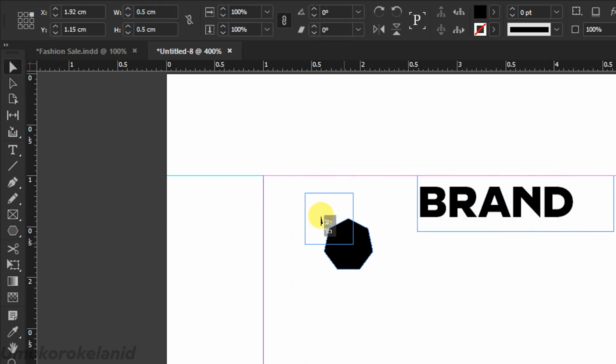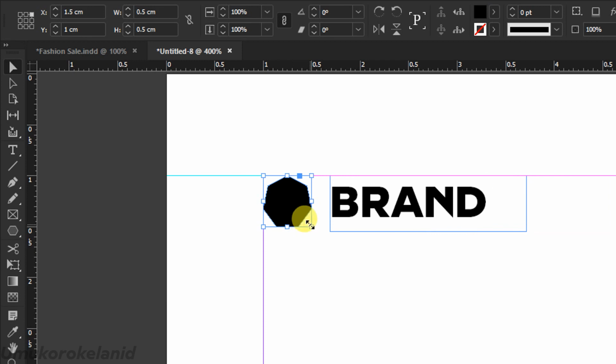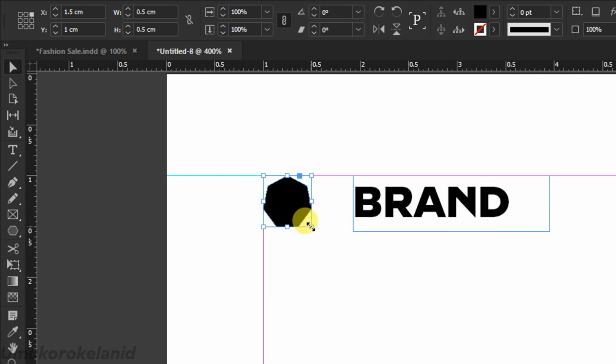Then we can position it well. We can decide to increase the size of the polygon. You can do that. We can adjust the size proportionally by dragging the shape and holding down the Shift key to drag and increase it sideways, but to drag it at the center and increase it proportionally from the center, we hold down the Alt key.